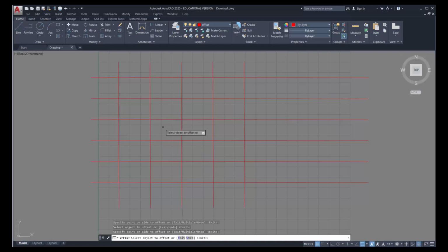Now Offset can also work on objects. These would be construction lines. And the nice thing about construction lines is we can create a grid and then actually draw over top of it. So let's go into the Offset menu and select Object. And now click on the Line tool. And you can see how I can actually select different points and simply draw an object based on a grid I made. It's a very quick and precise method of drawing because the offsets, even though I've only put in 1, it again is the 16 decimal place accuracy.